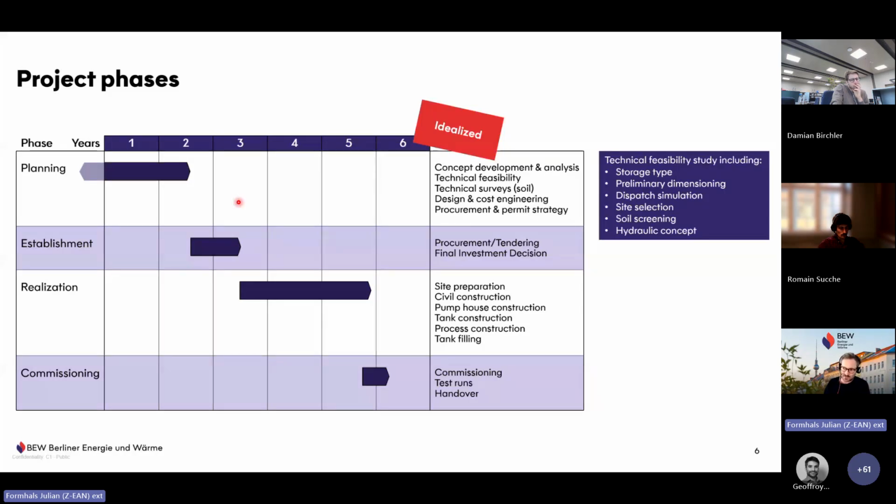And then, at this power plant location, we have a three pipe system with two supply lines and one return line, where one supply line supplies a constant temperature of about 110 degrees, and the second one is operated under different temperatures according to the ambient temperatures. So that was quite challenging as well, to see how to fit that into our system here.